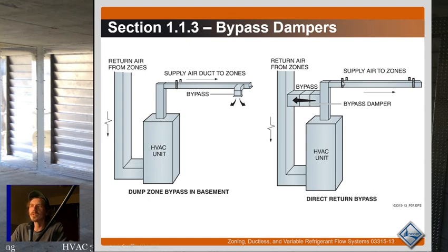So especially with circulation pumps, but even with air fans, remember you always balance on the supply side. You don't balance on the return side. The only balancing you should do on the return side is to maintain minimum CFM drawing from a space. You should never close off that side to lower the amount of airflow or water that you're moving in a system. So hopefully that explained it well.